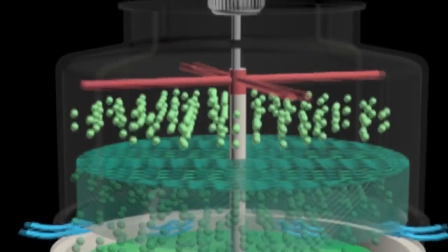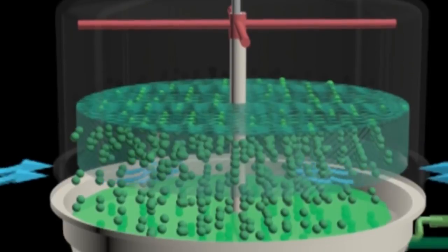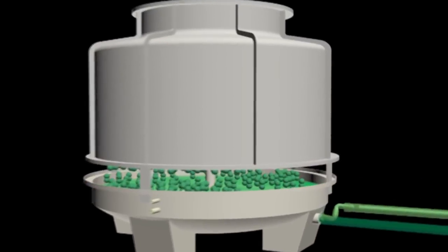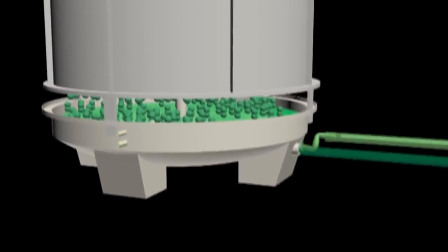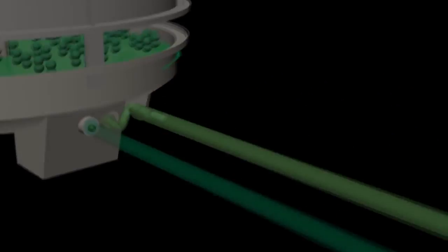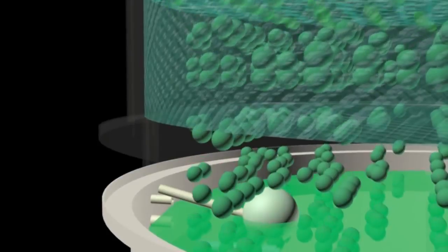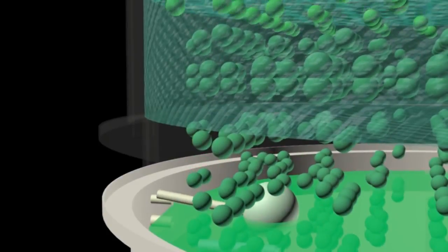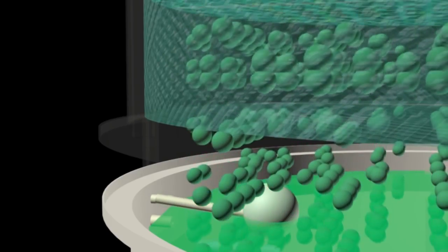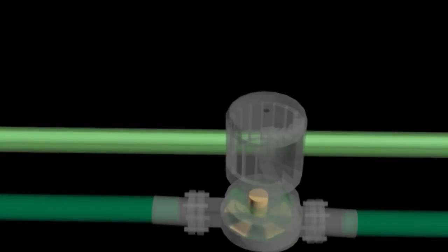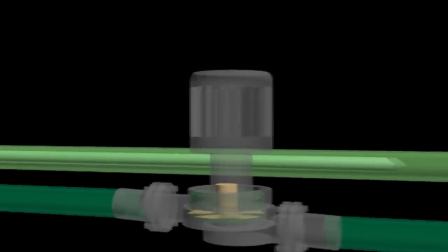Condenser water which has eliminated its heat to the surrounding air will accumulate in the basin under the cooling tower. Condenser water flowing out from the cooling tower to the chiller is called condenser water supply. This condenser water will flow back to the chiller to continue absorbing heat from the refrigerant. The buoy system at the water basin is connected to the make-up water tank. It works for adding water when the water level in the basin decreases to a certain level due to evaporation. This condenser water cycle will continuously flow as long as the centrifugal pump is in good working condition.